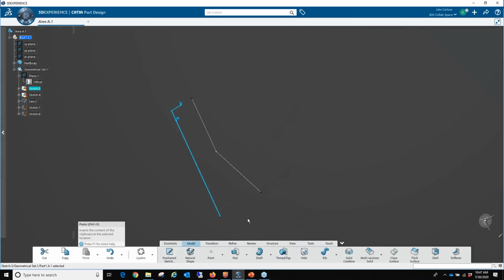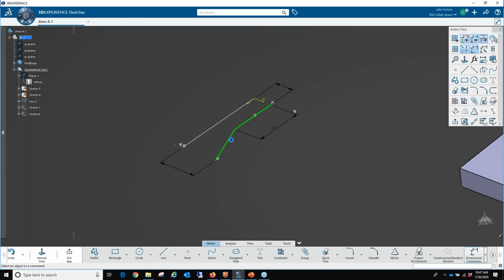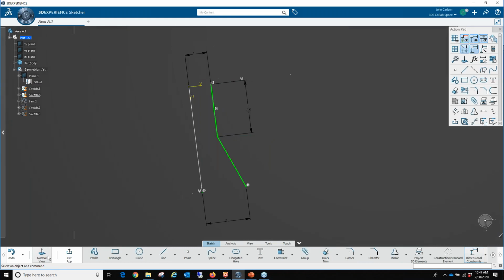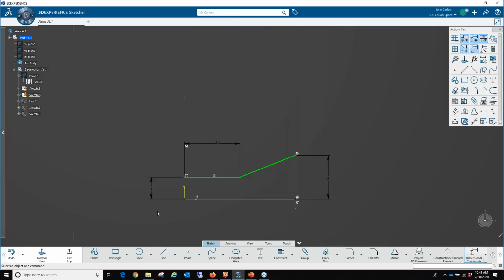Now the second sketch I've got here, again, if I double click on it, this is the actual one that will control the size. Again, get myself turned around into the normal view. And then notice I just got a dimension here, a 1 at the beginning. So that means that I'm representing that as a radius of 1. So my size is going to be 3.14 square units at that end. And then over here at the other end, I've got this dimension as 2. And so that's going to end up being the 12.56 with that.